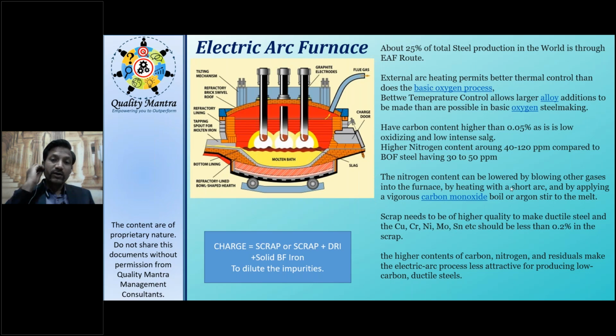So where there is static or dynamic loading, high amount of loading, people use cleaner steel. Cleaner means lower amount of impurities, and nitrogen and oxygen are also one kind of impurity. So the lower it is, the better the quality of the steel.